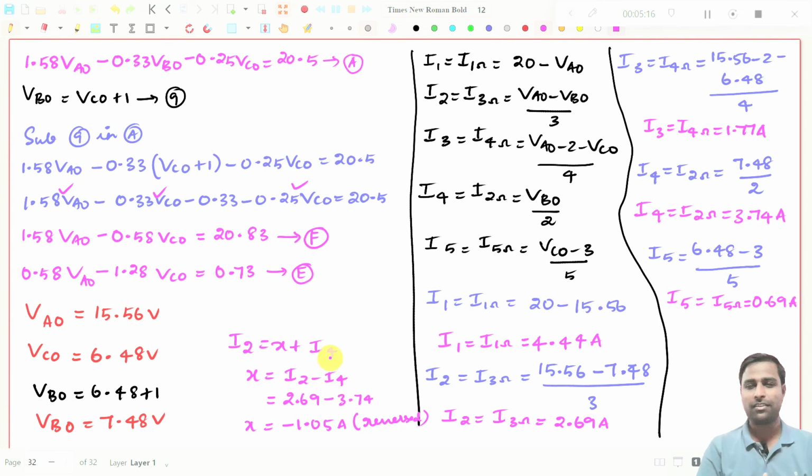So, this is the procedure to find all currents in a given circuit. That circuit is a super node circuit where it contains a voltage source between two nodes. So this is the simple procedure to find the current values. And also you see we have found this by using KCL, right? And we can also find the currents by using the matrix method. That will give you better clarity towards the problem.